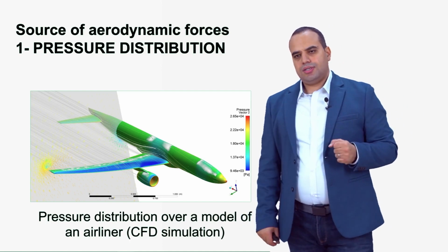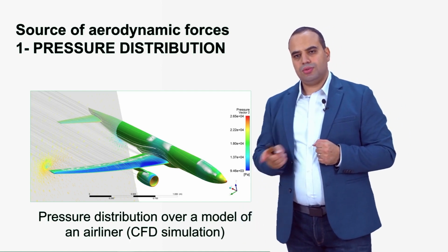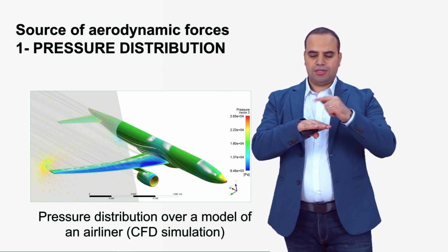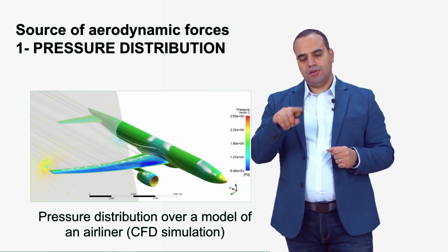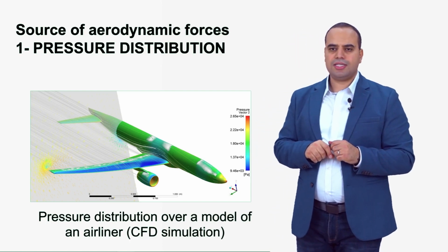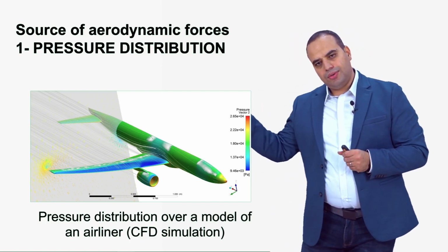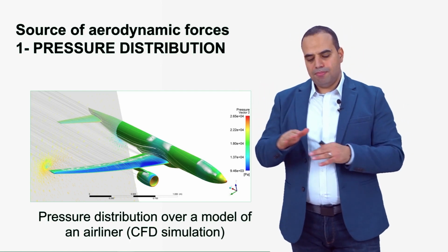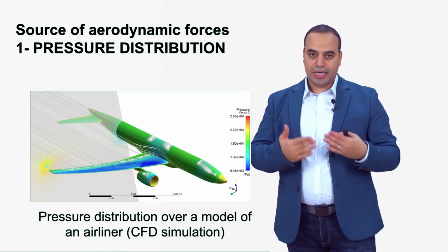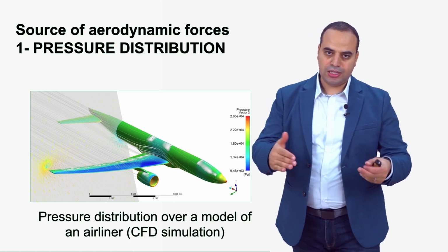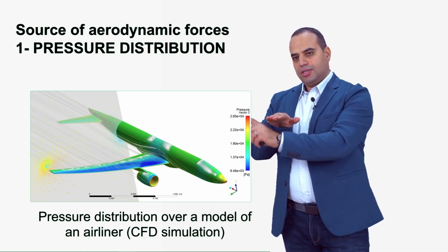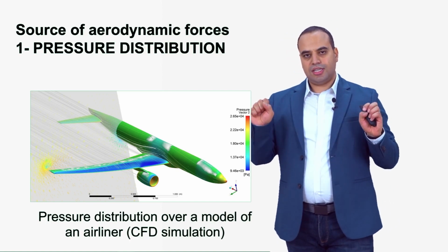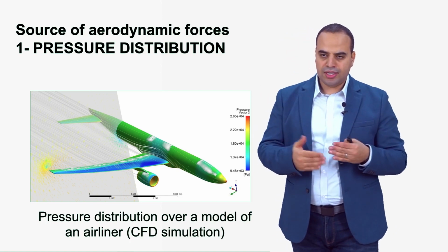And we can see some other things here. For example, the wingtip vortex, at the tip where the wing ends. There is a vortex motion of the gas there. And inside the vortex, if you look closely, you can see that it is blue, right? That means there is low pressure, which is a drag, right? Because the aircraft wants to move forward, and this vortex, which has low pressure in its core, is sucking the aircraft from backward. So it is also a drag, right?